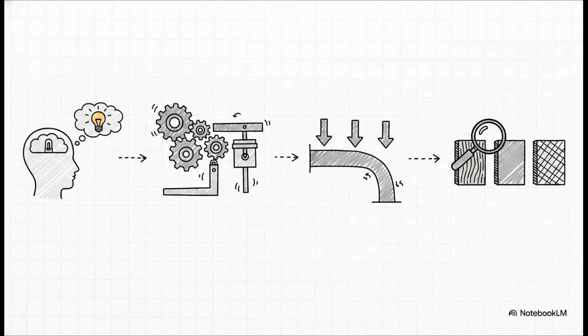Guys, this is absolutely crucial. You must find the forces acting on every single member of the machine and calculate the energy being transmitted. Because only after you know the forces can you move on to step 4, material selection. You have to pick the material that's best suited to actually withstand those specific forces.